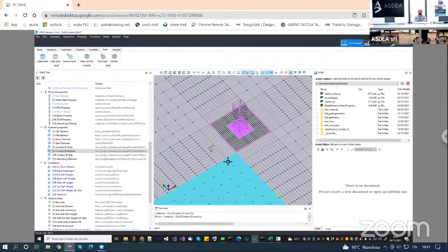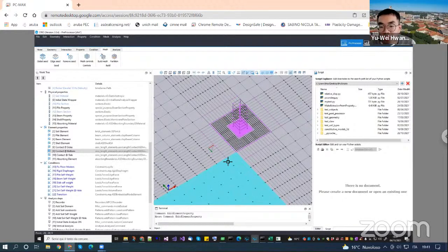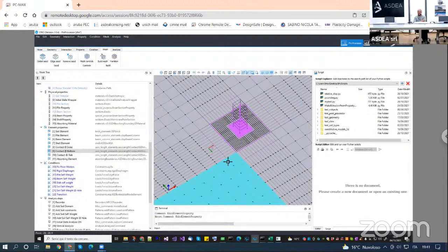In the FLAC manual, they also mention that if your soil domain is nonlinear, you will expect some very weird displacement along the boundary. So I think this is something they haven't figured out yet. But the nice thing is that I don't want to test it on this kind of absorbing boundary, because in OpenSees there is another tool that we are testing now with the professor who implemented it, called DRM.